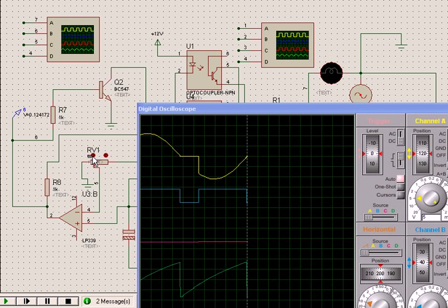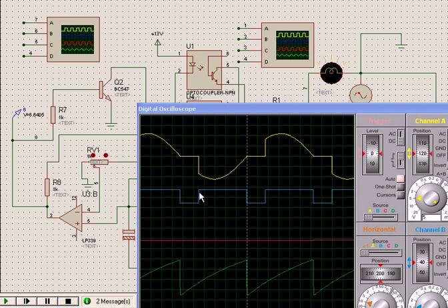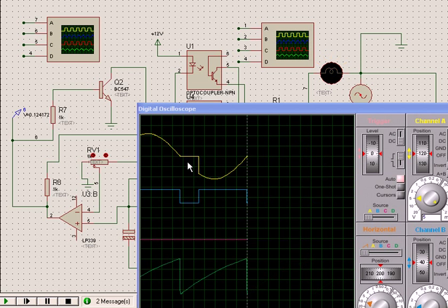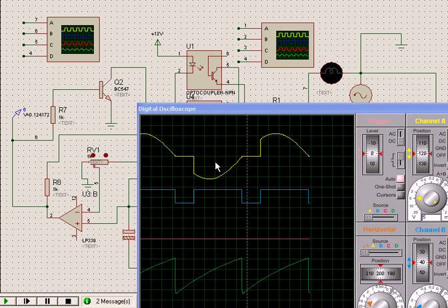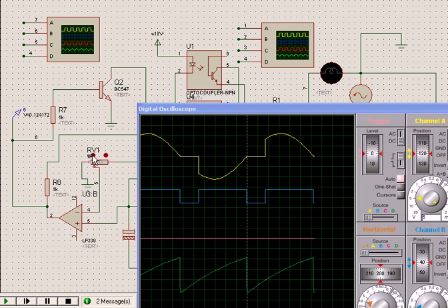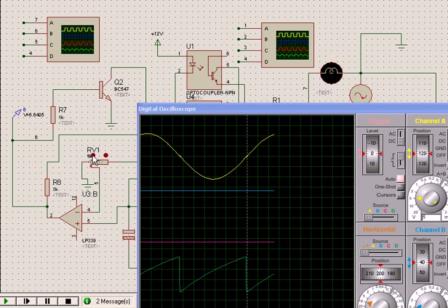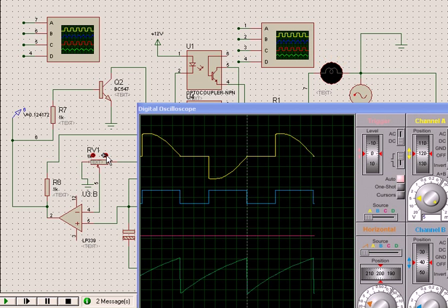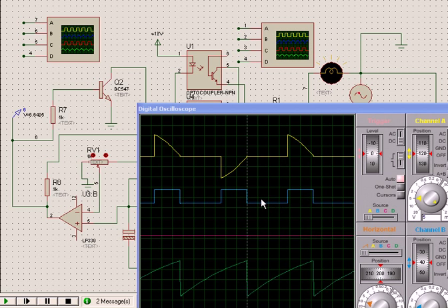See the output. The width, this is the off time. During the off time it is off. During the on time only the output is on. And this is based on the ramp and then the level, which we have all discussed in separate audios, and that is how it works. Now if I go this way, finally full output, and here a little less, further less, further less, further less. You can see this is the off time.